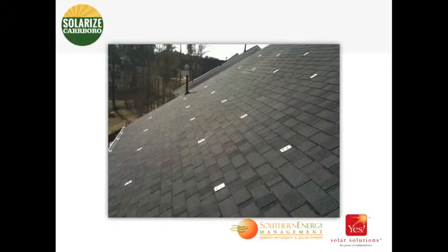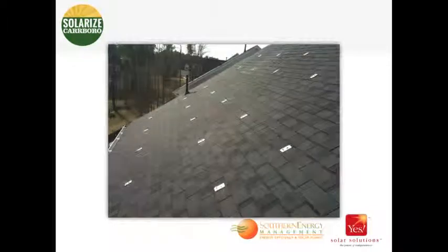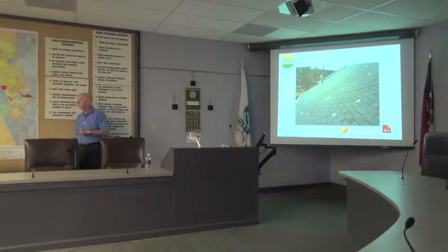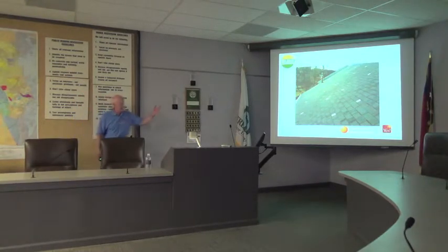We want to penetrate into your rafter. That's how we're going to secure the system itself. That penetration is drilled into the rafter, we fill it with sealant, and then we put this little stanchion on it. So that kind of starts the process. And of course, we have laid out the array as a result of what the design system was initially.